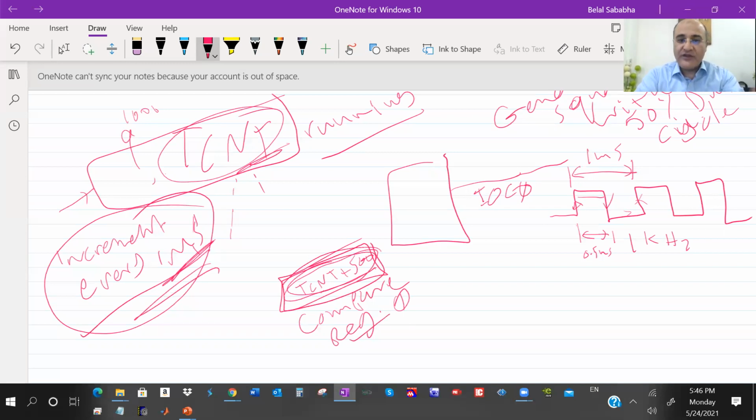register. Now there is hardware that will keep comparing the value of this register with the value of this register. When they match, you pre-configure what happens on the pin. You say, when these match, generate a rising edge. Then you get interrupted and notified. You say, okay, after another 500 microseconds, I want to do a falling edge.